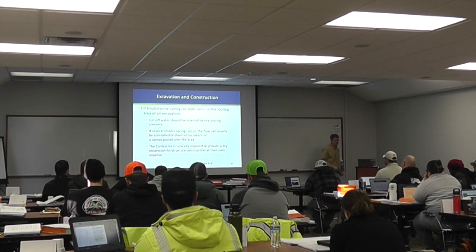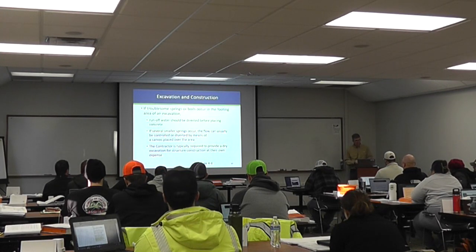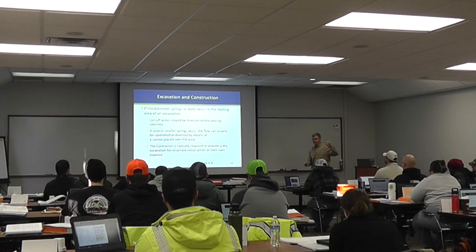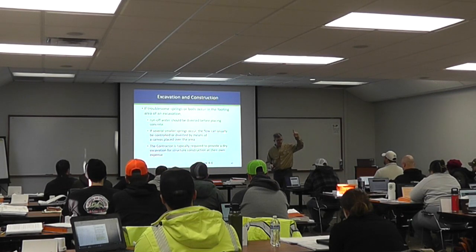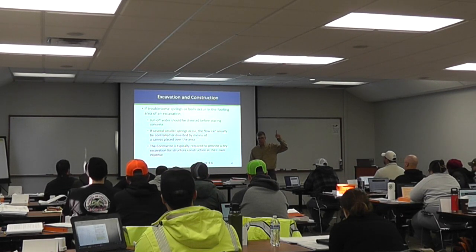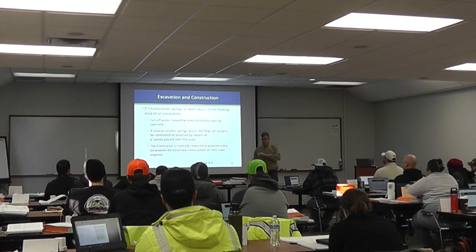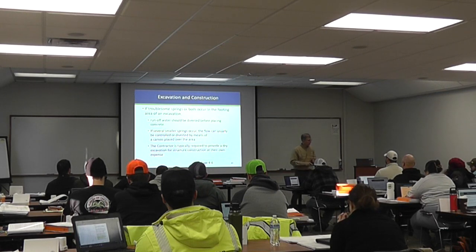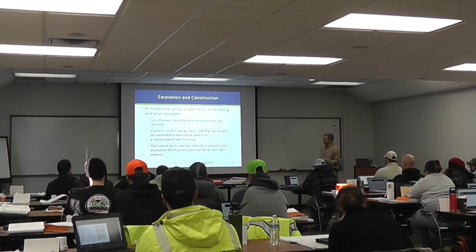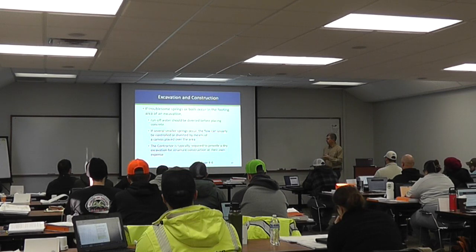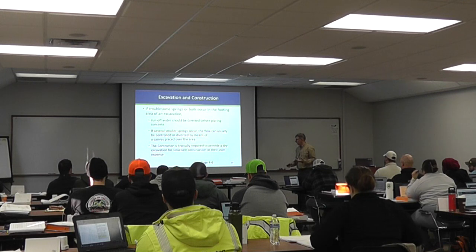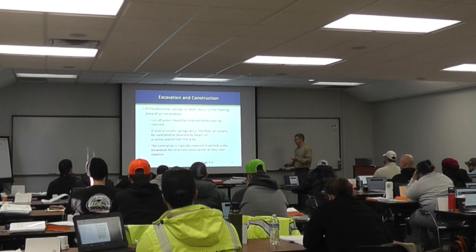So just a couple of slides on if there are some troublesome springs or boils, what do we do? Do we mix it in? No, because what's that going to do? It'll reduce concrete strength by increasing the water cement ratio. So in structural engineering and in all concrete, we're concerned about water cement ratio. So we don't incorporate the water. It should be diverted. If there's smaller springs, we can use a canvas or something. They have to provide a dry excavation.